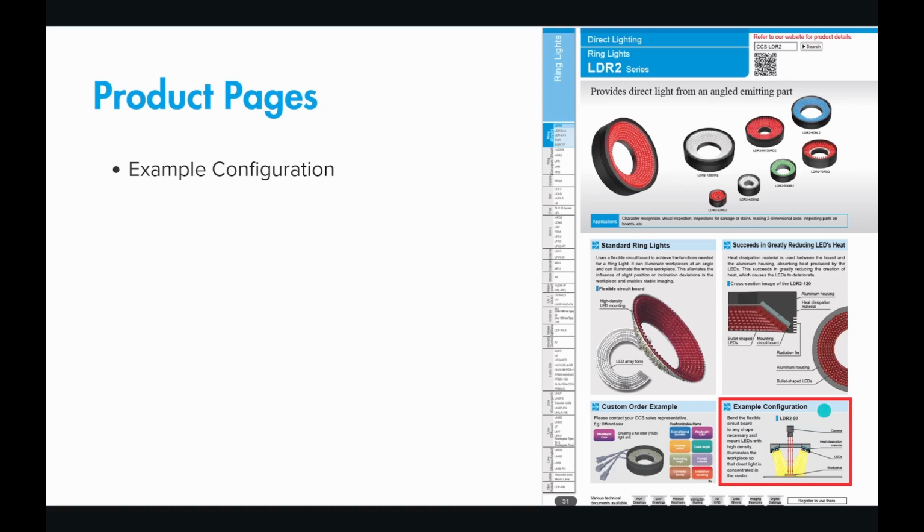So if you're doing testing and you decide that the light solves your application best, if it's a ring light placed at 30 degrees, then place your ring light at 30 degrees when you're solving your sample. Do whatever testing solves. This is just meant to be a reference on where to start and to show you how the light was designed.